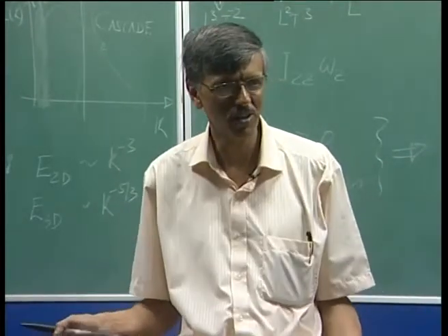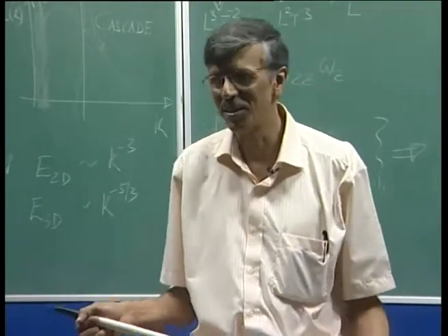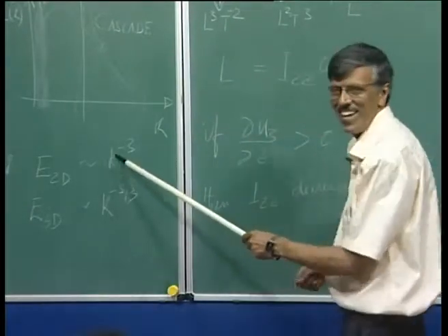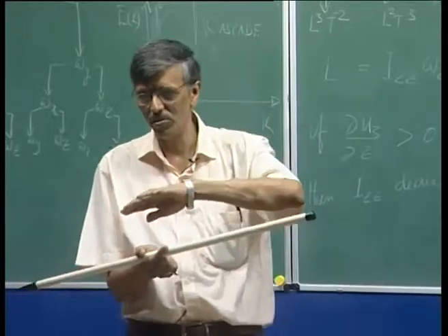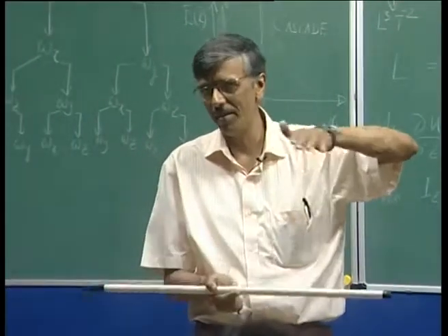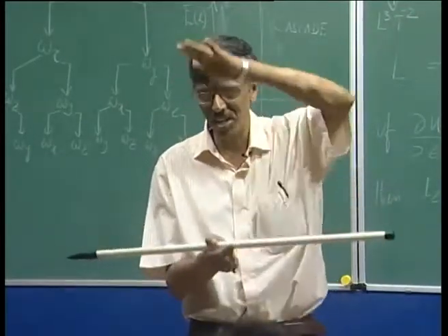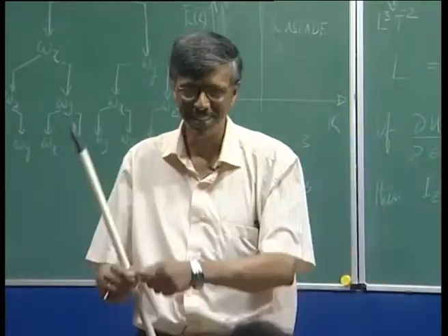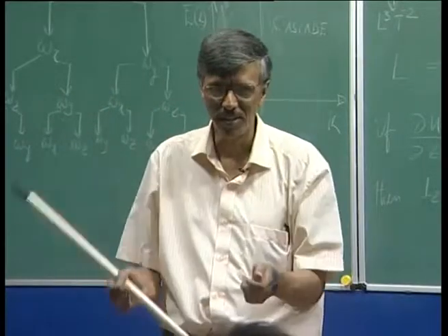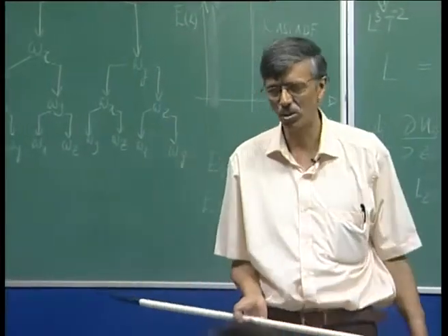An interesting part is, you look at our weather system, you will find first you get this k to the power minus 3. So, weather prediction has actually survived by treating this flow problem layer by layer. In each layer it is a kind of 2D problem. 3-dimensionality is stacked one over the other, like an onion peel, you can peel out one layer over the other, but mostly the dynamics is dominated by this 2-dimensional motion.